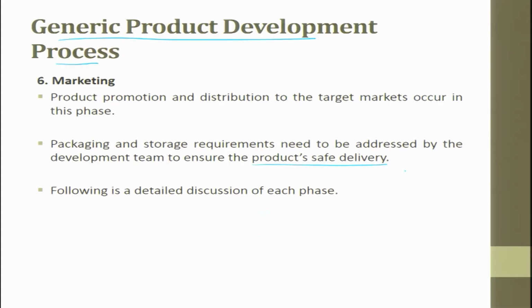So, today packaging and storing is also being addressed in concurrent engineering, and it is given importance right from the design stage itself. For example, if you try to make a large projection of a solid block and then you want to pack it and send it, and if it has sharp edges, it is going to poke, it is going to tear the package material. So, right in the design stage itself we work back and start removing.